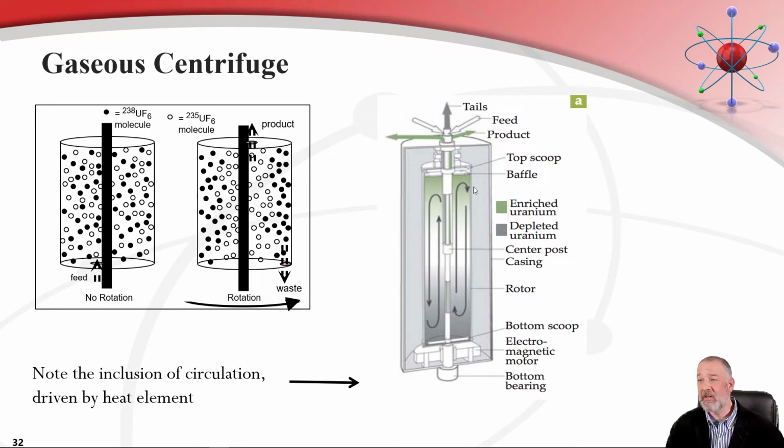To put it plainly, if there was air around the spinning cylinder, then it would create drag and friction on that spinning cylinder, and it would be a lot less effective than if it had no drag. And that's all that outside cylinder is for: to create a vacuum so that when we spin up the rotor, it's not going to experience any of those frictional drag forces from being surrounded by air molecules.